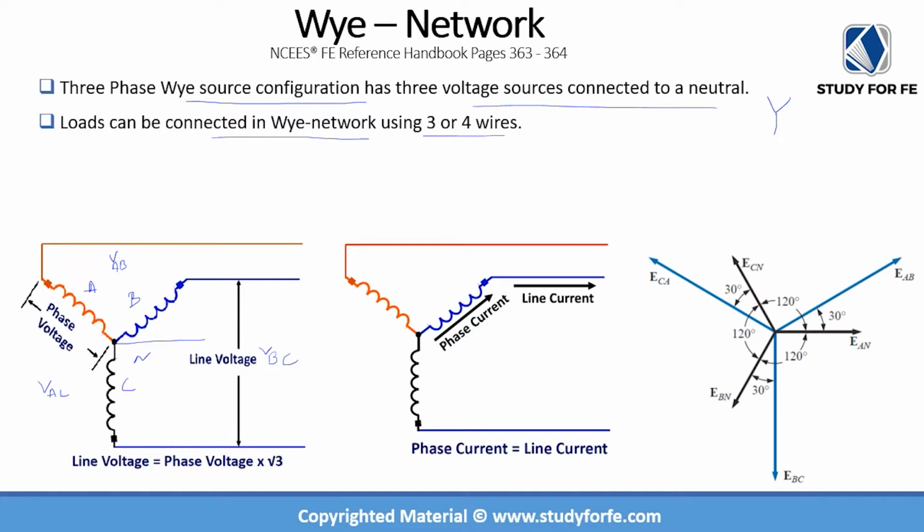So you might introduce, for example, if you have an MCC feeding a bunch of motors and then you have utility panels, then sometimes the MCC would still stay as a 3-wire system, but downstream of the MCC you will introduce a dry type distribution transformer, and you will derive a neutral from the distribution transformer, which will be feeding a distribution panel, a lighting panel, and so on and so forth. So rather than bringing in 4 wires from the service, you basically generate neutral close to the load.